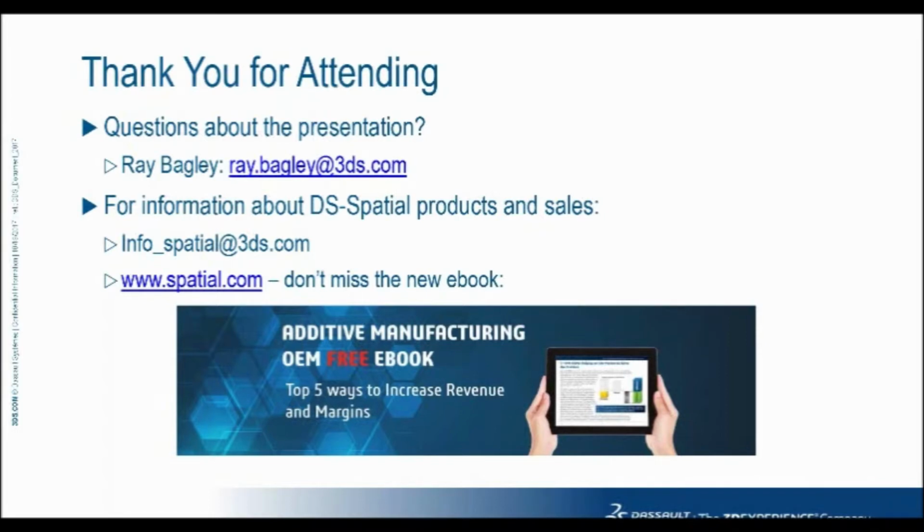I don't think that they should, and I'll tell you the chief reason why. It gets introduced in the world of translation. Each mechanical modeler has a definition of its core resolution, right? How close can 2 points be and still be considered separate, versus when do they just merge together in numerical noise? But as you translate data from one system to another, from CATIA to STEP or CATIA to NX or something like that, each system has a different tolerance and even a different scheme of how they use those tolerances.